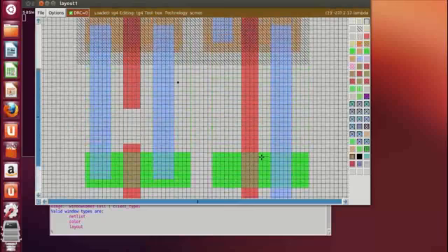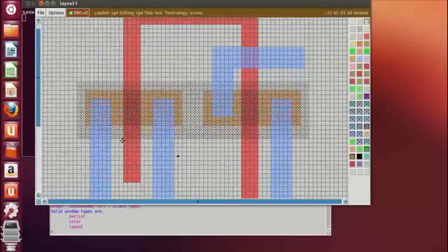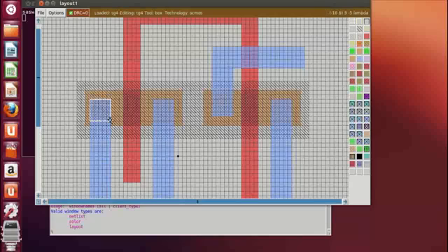Okay. Now I'll place the other contacts. How will I do that? Select, same procedure. Only thing we have to search the contact. So the contact over here is the P diffusion contact. This is the N substrate contact. This is the ND contact and this is the P diffusion contact. So here the P diffusion contact. Okay, so here similar way select and this is the PD contact.